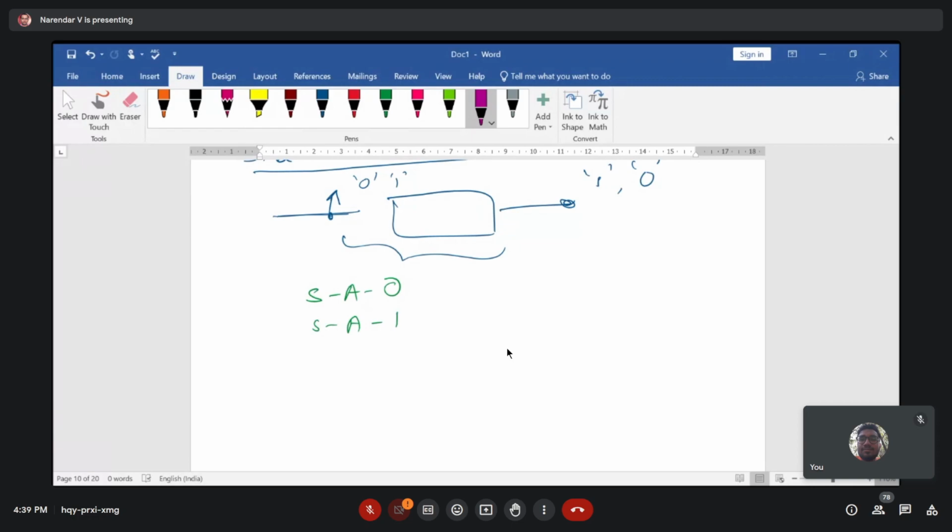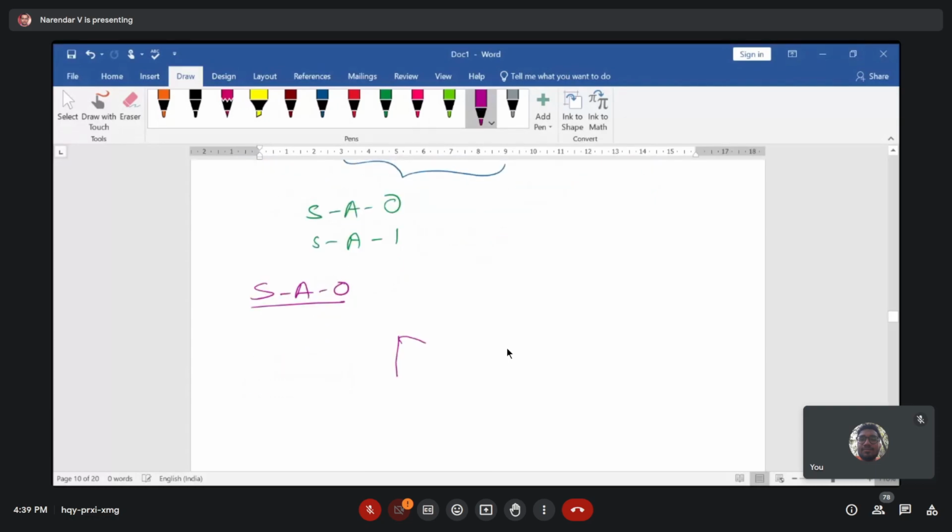Let's take an example of an AND gate which has two inputs and one output. The output is F, and the inputs are A and B. A stuck-at 0 fault is a line, A or B, let's take B, which is always connected to ground. It means as you change the input of B to 0 or 1, it cannot be reflected to your logic gate.